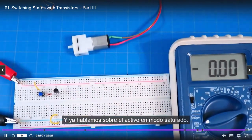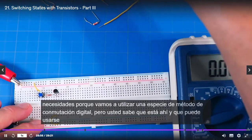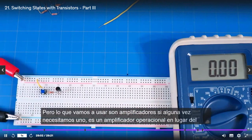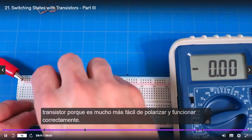And we talked about the active and saturated modes. We're not going to worry too much about the active mode of the transistor for our needs because we're going to use it in a digital switch method. But you know that it's there and it can be used as an amplifier. But what we're going to use as amplifiers, if we ever need one, is an op amp instead of the transistor, because it's just much easier to bias and get working.